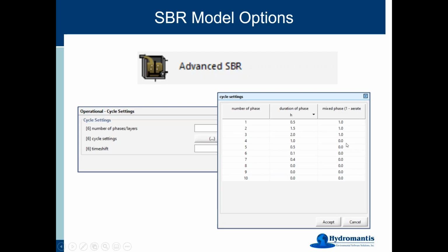So we're going to go in the CSTR mode. And if it's 0, that means we're going to flip over to the settling mode so that you can have the one-dimensional concentrations in your SBR. So typically that would look like, for a conventional one here, maybe those first few you're doing some filling and mixing and aerating. And then these later ones, you're just doing settling mode and decanting and letting the rest of the system settle before you waste and so on. So lots of flexibility here, as I mentioned, to do multiple things at a time or to repeat phases if they're part of your cycle.